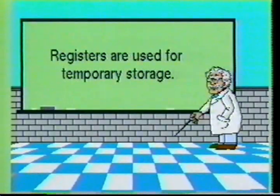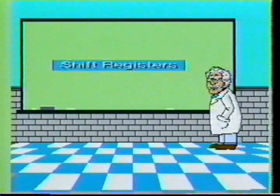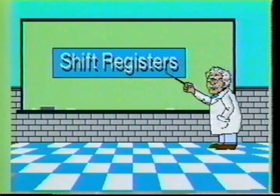We will now pause for a short review to reinforce the important concepts of the registers just discussed. All registers are basically a storage unit used to temporarily hold information until the information is requested by another part of the digital system. The most common storage register is the shift register. Shift registers are generally classified by the method in which the data inputs and outputs to and from the unit.